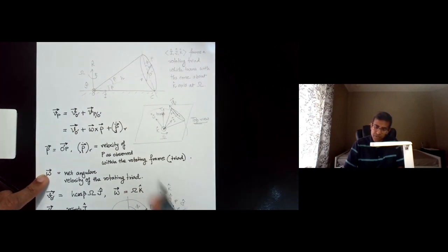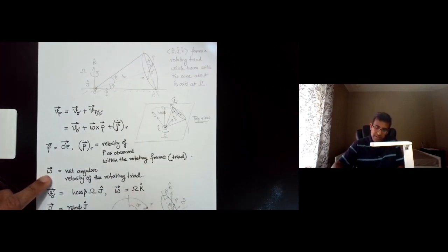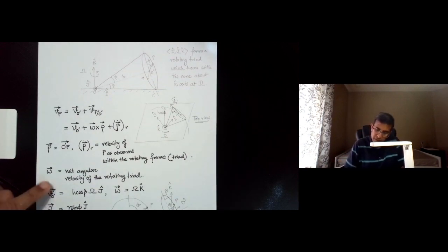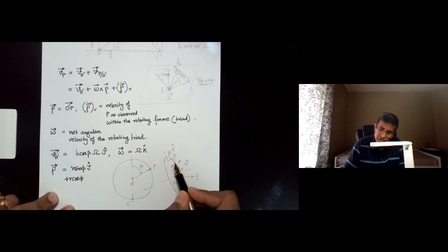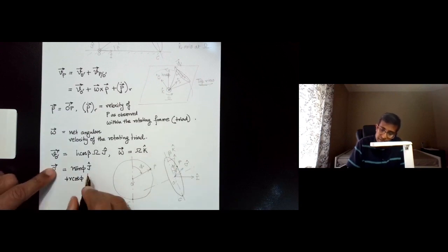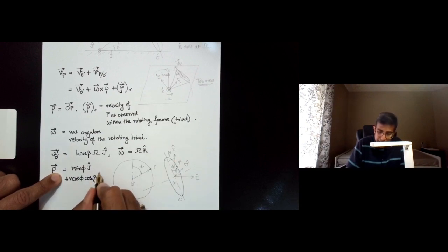So this line makes an angle beta with respect to the vertical, by virtue of the fact that the base circle is tilted by an angle beta. So r cosine phi is going to resolve O prime P along this inclined line, and then cosine beta of that is going to resolve it along k hat.